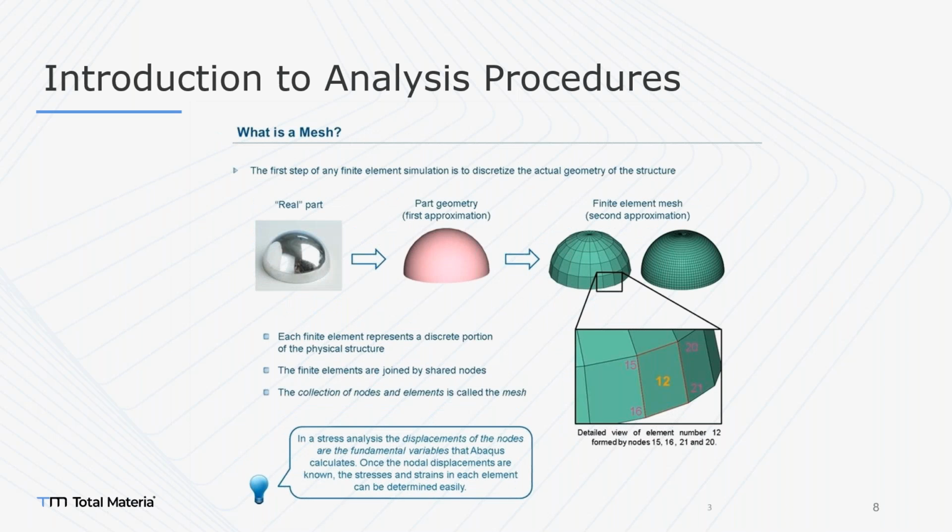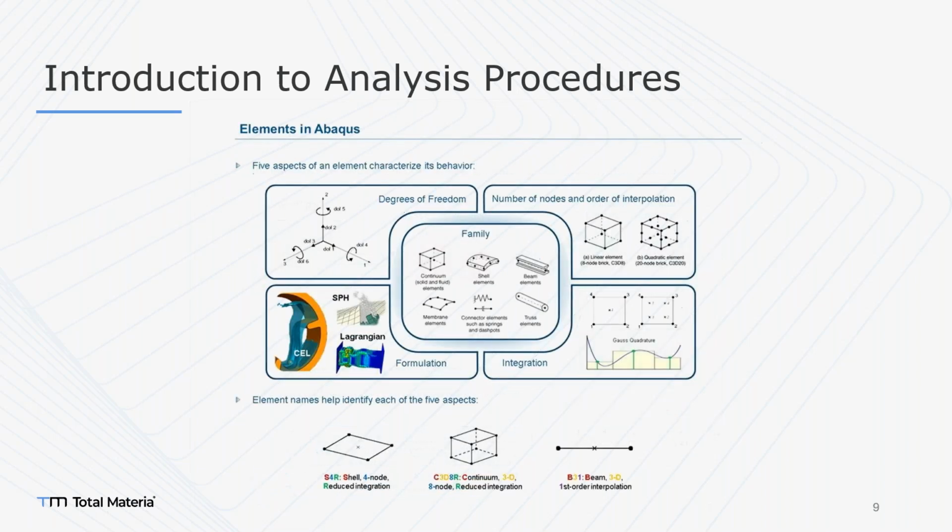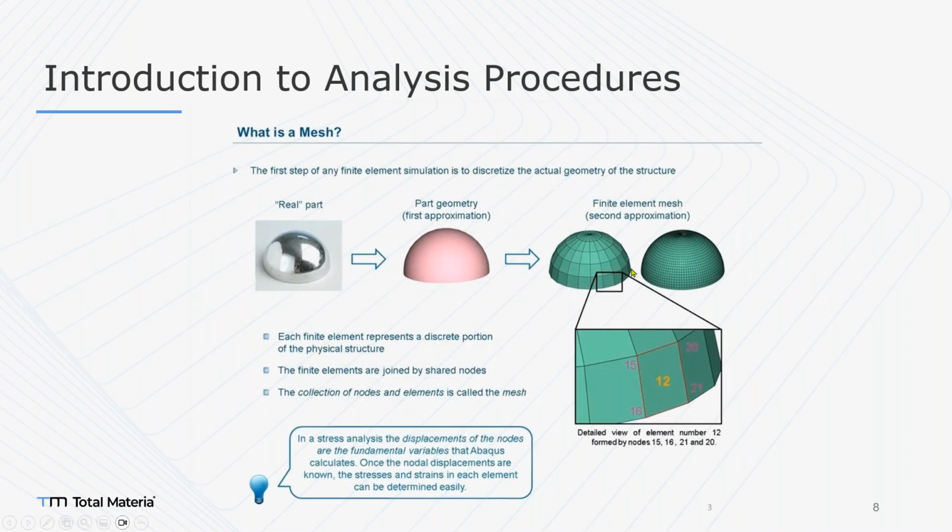Another thing is that the mesh is really a team player in our analysis. You should consider what the mesh is, what the element IDs are, what the node IDs are, and how they will be a perfect match. We need to consider that. We are looking at a mesh right now, and we can see that there are also quads and rectangular areas here.